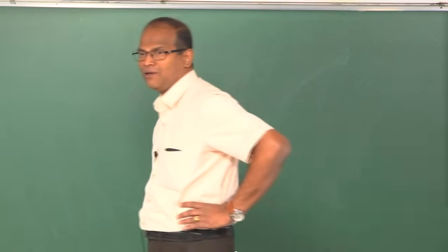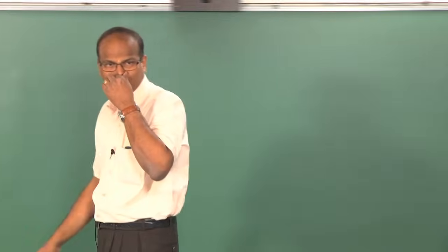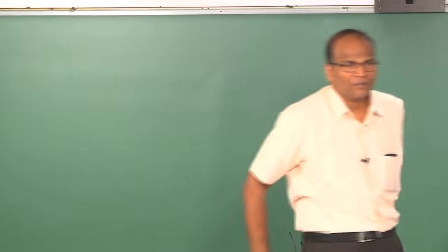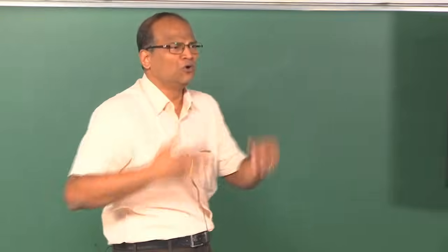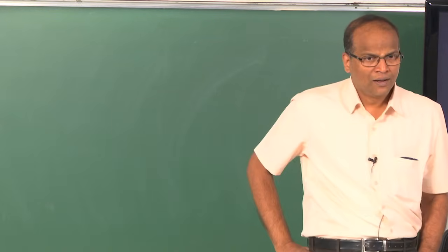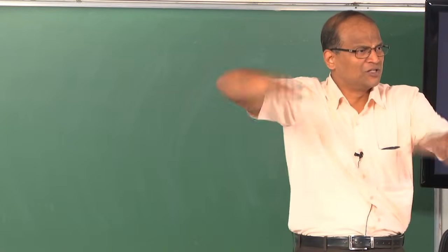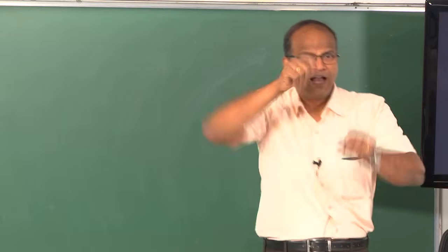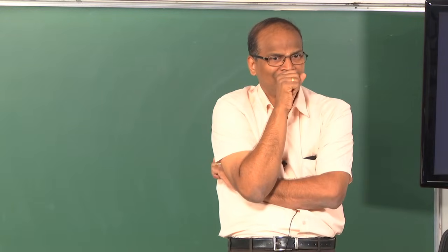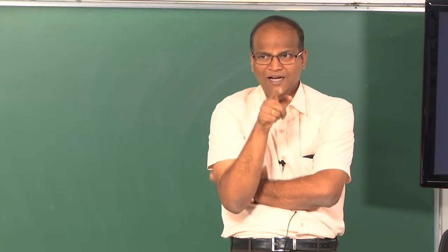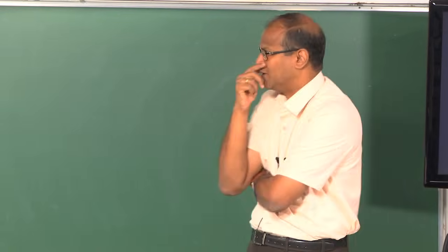How do you design an experiment? How do you measure a flow rate? How do you measure pressure drop? If it is a huge pressure drop, you cannot use a U-tube manometer. What is the maximum h? How much? Or will you climb a ladder to find out what that h is? Are you getting the point? So knowledge is very important.